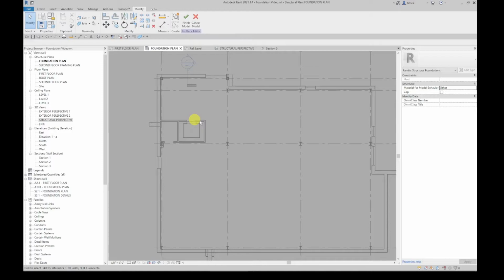So what I'm going to do is I'm going to jump across that door opening, and I'm going to create another sweep. So I'm going to click on sweep, I'm going to sketch the path, and now I'm going to go from that side of the door to this corner, and I'm going to come over here until the endpoint of my window wall, which is right there. Now it should find that point. I'm going to hit escape. I'm going to hit the green check mark. So I'm finished editing my path.